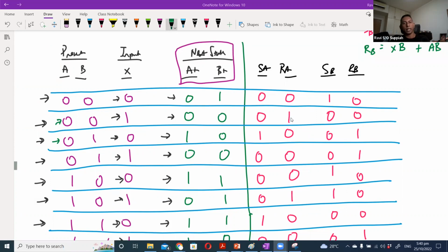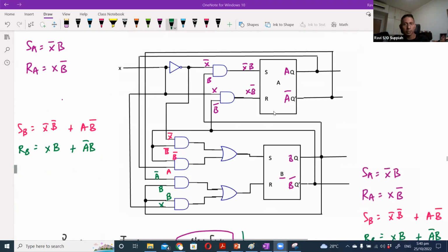But if I just take the circuit as it is, and there is no reset line, then each time I power up, it may actually have a different starting point. That's the truth, because you can never predict exactly how all the different signals will stabilize and eventually trigger the flip-flops to give you one initial starting point.